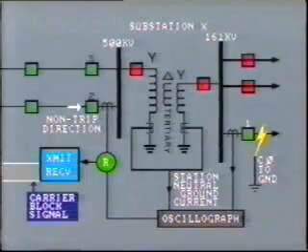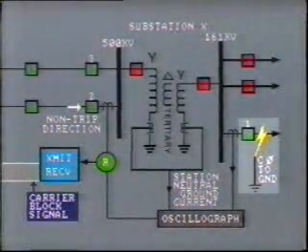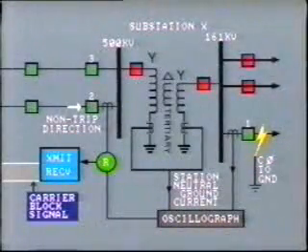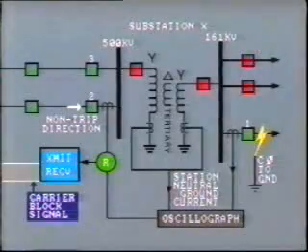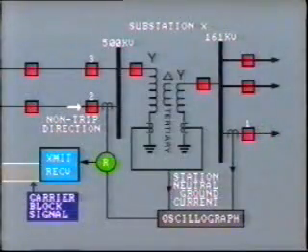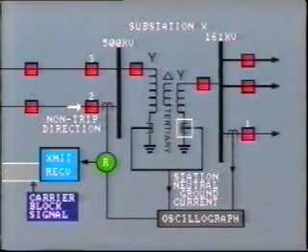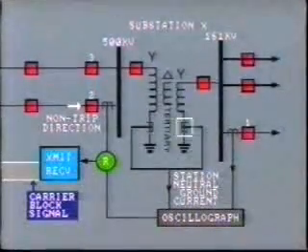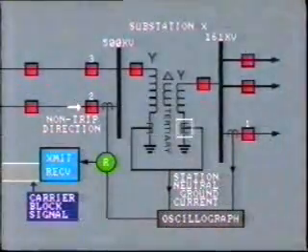This allows the breakers on the 500 kV system to falsely trip for a fault on the 161 kV system. As before, this was a temporary fault, so all breakers reclosed successfully at high speed. The problem was solved by replacing the 161 kV neutral CT with one having better operating characteristics.